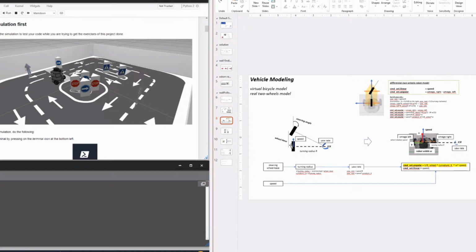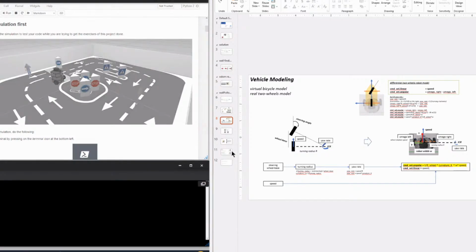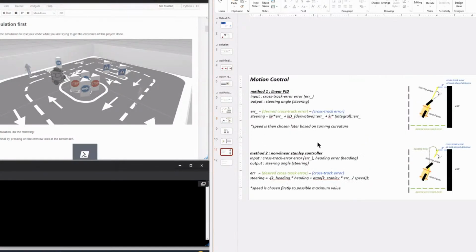Okay. And here, as we can model the wheelbase, when we change the wheelbase modeling here, we can really change the behavior of the robot, because the wheelbase will affect the turning radius. So when we change the wheelbase here, the robot could turn more aggressively or smoothly. All right. Okay, so I have some modeling parameters that I have to test and try, and controller parameters also to tune. So you can tune it.